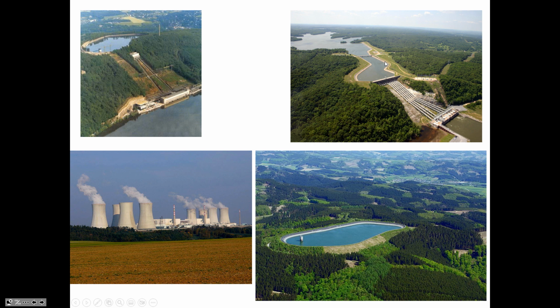So now, what this pump storage system allows you to do is use electricity at night when it's cheap, and what they'll do is at night they'll pump the water from down low and pump it up to the elevated reservoir. And they'll do that at night because nuclear power, for example, is really hard to turn down instantaneously when there's less demand at night.